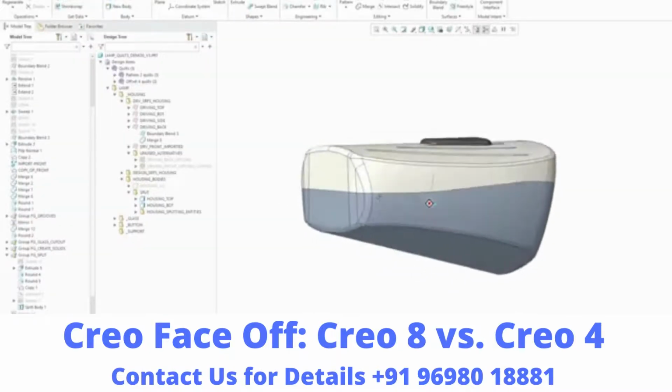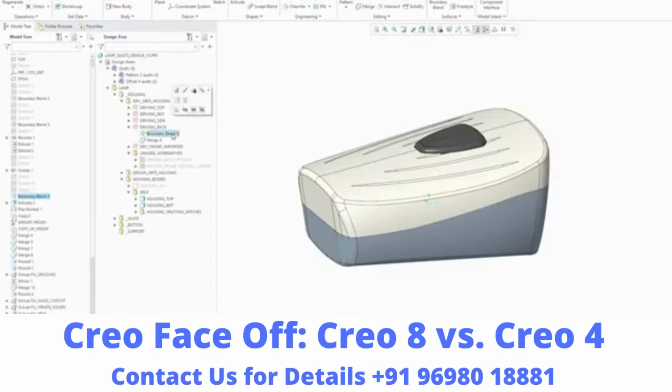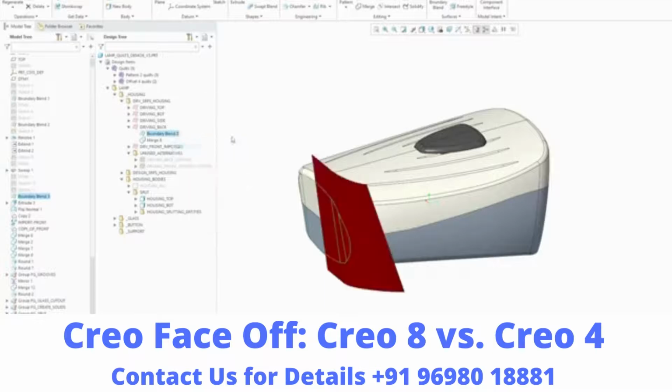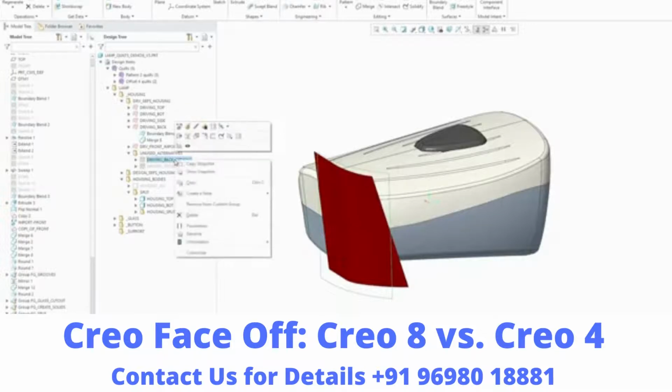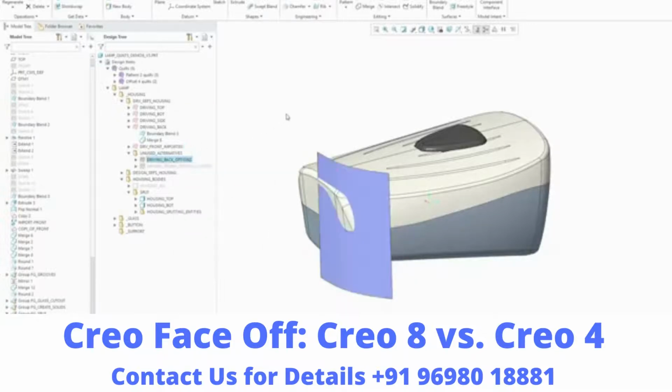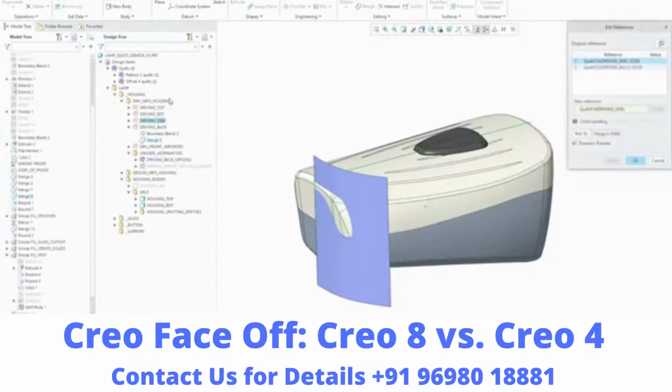Additional intelligence and capability has been added to the Replace References command. When replacing references in previous versions, users could select alternate references for the parents of the replaced reference. Only direct children and their respective references were considered during the replacement workflow. This, however, could cause issues with other features. In Creo 8, Replace References has a new Recursive References option.